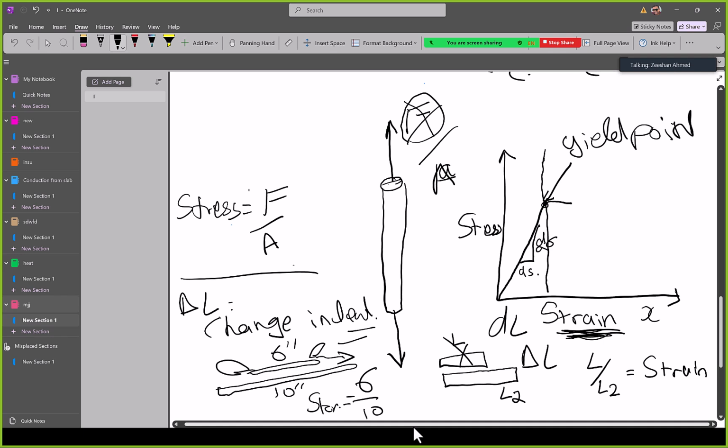And ladies and gentlemen, this yield point is what defines the grade of the steel bar. Grade 40 and grade 60. It is this point where we identify the quality of steel, because we have to keep the whole design behind this point; we should never go into permanent deformation. So if you are going to the market and your client is asking which rebar to take, grade 40 or grade 60, you tell him, take grade 60.